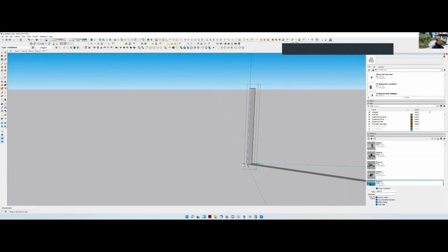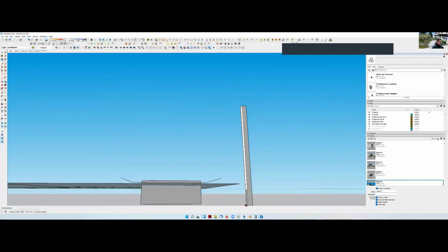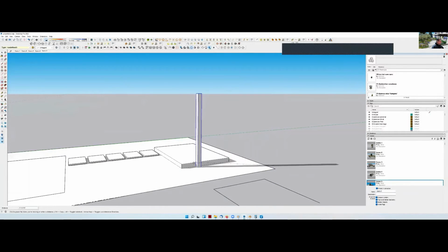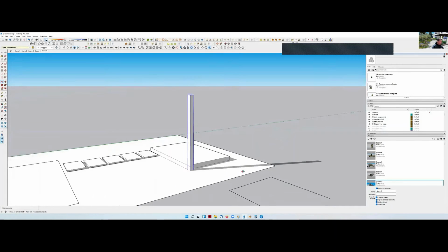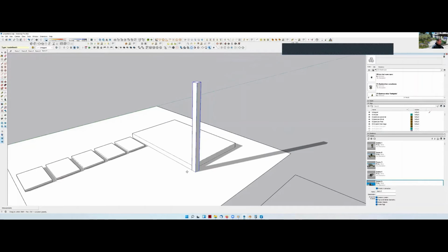And I am going to create a column or the post at 8 feet tall off the ground, and then I'm going to copy the bottom another 2 feet to represent the space going into the ground. So it's a 10-foot overall 4x6, and then I'll just set this line so it's at the surface.